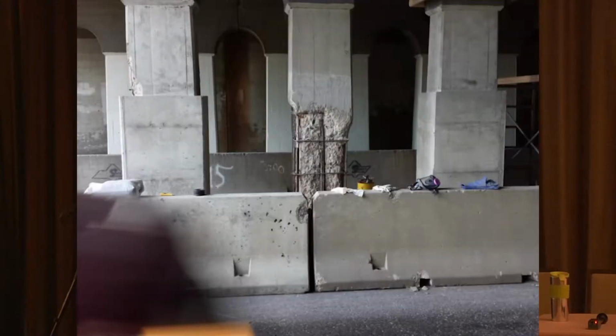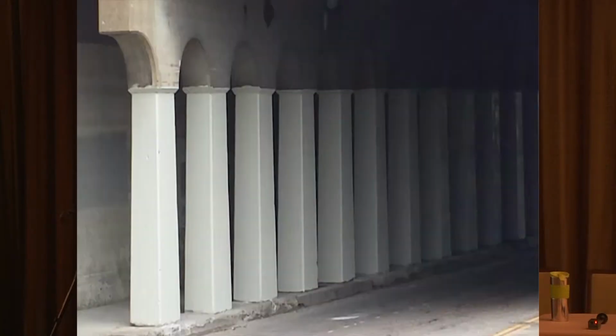And this is what we ended up doing on this. You'll see on some of the piers in the center there, they're still being exposed, but you can see that we've gone in with an overbuild on this, putting in those galvanic anodes to protect those piers. And this is another area on that very same project in which we've done an overbuild with the galvanic anodes, the distributed anodes underneath.